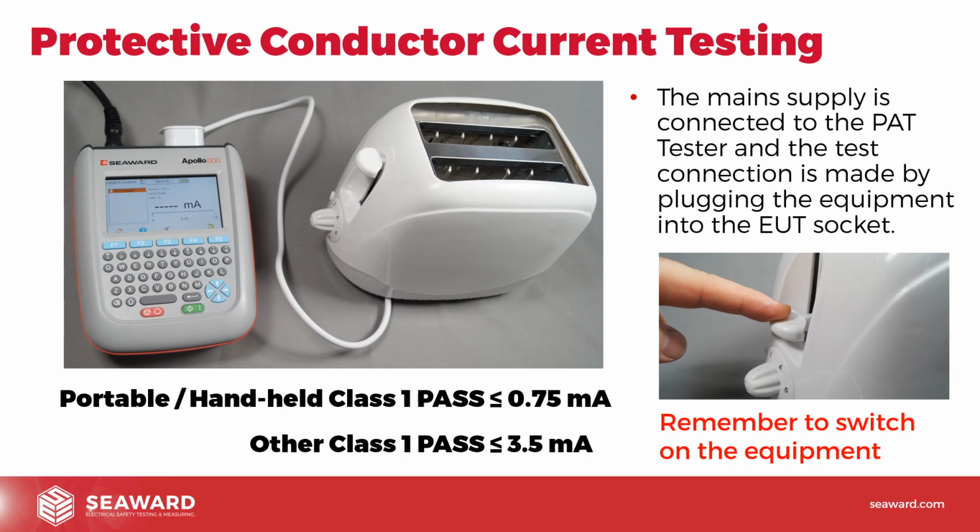Now, obviously, the thing we need to remember there, like the pictures and the little measures there, is we do need to have the equipment turned on. So once the test has started, we would need to actually turn the equipment on to make sure that we are fully testing the equipment. Because if we don't turn it on, it'll do the test, but it's still only measuring up to the switch and not actually fully checking the equipment. So always make sure equipment is switched on at that point. And as I said, obviously make sure we've applied the safety precautions with that.